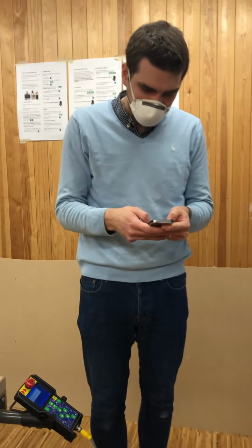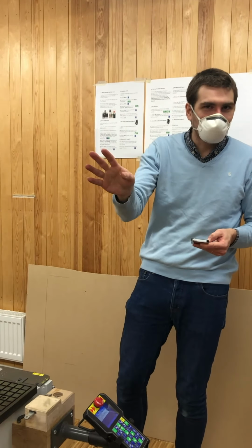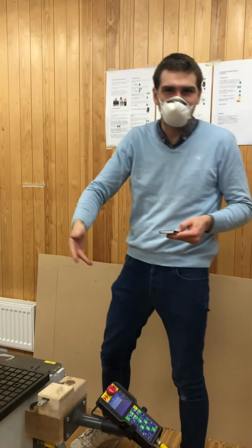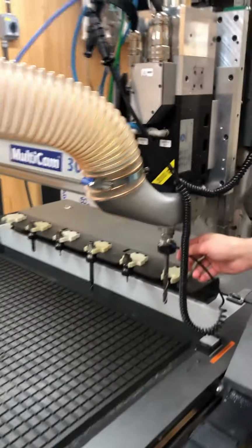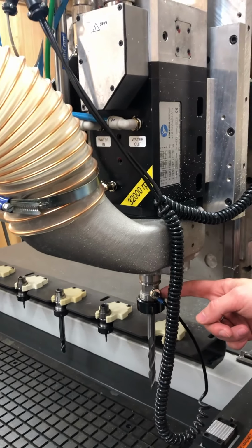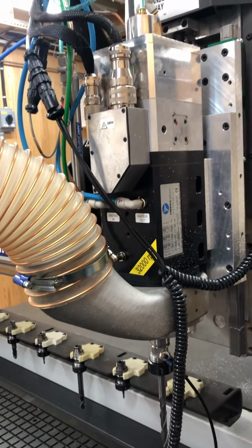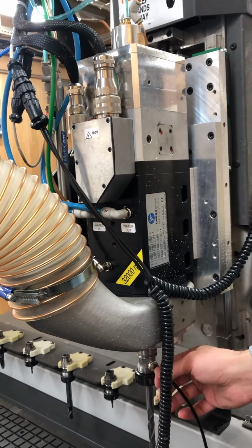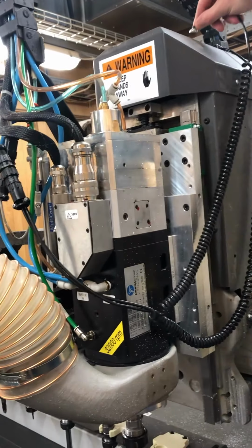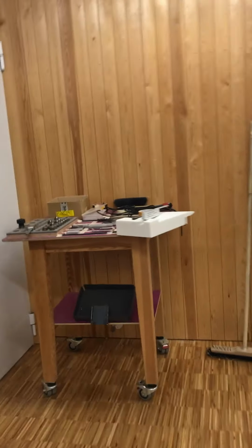The tool is now calibrated. We have made one mistake here, but it's not a serious one as yet, because we have not done anything else. So we should take off the magnet. Yeah, I forgot about that. But this is really important, because if one would have left it there and run it, then this would have spun around and it could be disastrous. So it's very important that this is securely attached to the top there. Sorry for that. But it's better to learn from my mistakes now than to make them yourself.